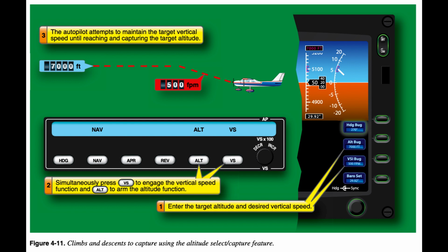Catching errors, armed modes help prevent forgotten mode changes. You have already seen how remembering to make a needed mode change in the future can be an error-prone process. Not canceling the armed function allows the altitude select mode to relieve the pilot from needing to remember to engage the function manually once the aircraft has reached the selected altitude. Do not interrupt the altitude armed or capture mode, unless prepared to manually control the process. End of page 4-8.